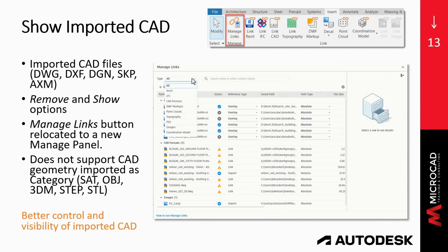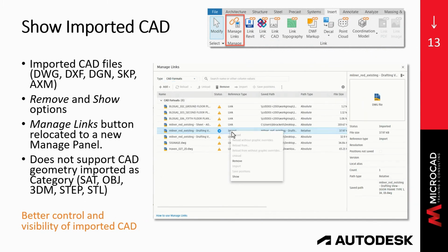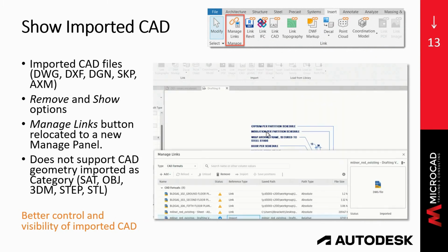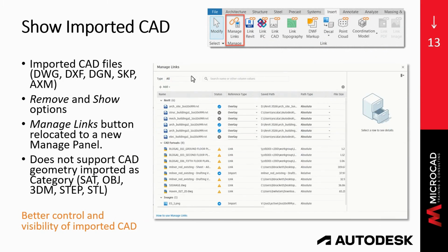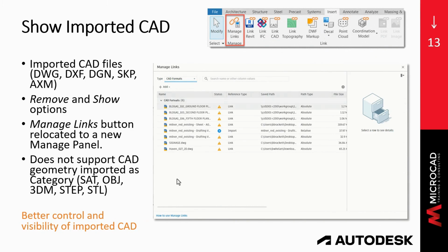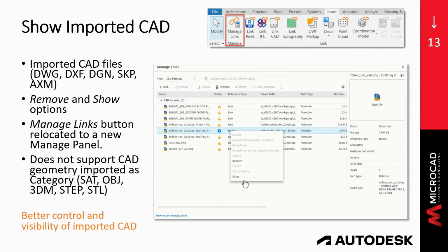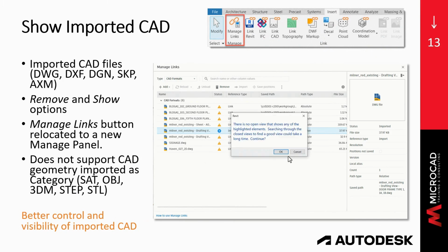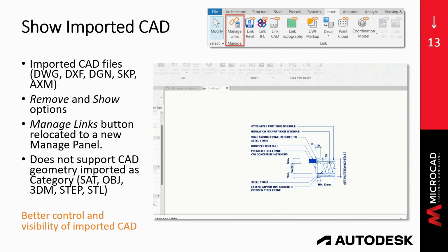And one huge thing is that the imported CAD files are being shown in the Manage Links dialog box, which is great. Absolutely great, because if you didn't know, imported CAD files would not show in the Manage Links because it was not a linked file. And now they show up and it's like, yay, hallelujah to that feature.